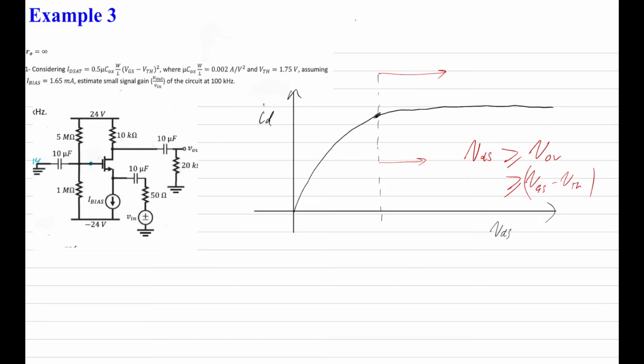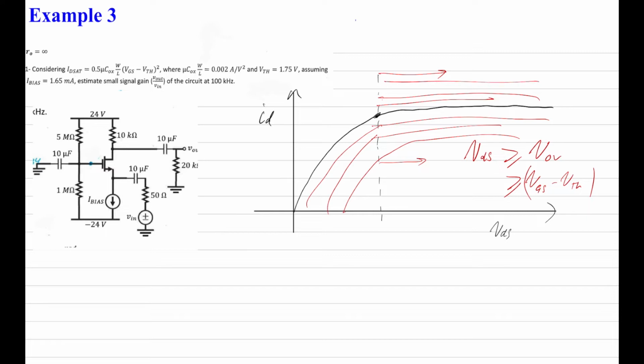So the only thing that really determines where this level is, if it's over here, or like that, or like that, is actually determined by one parameter, and that's the gate source voltage. So once we are in this region over here, we can adjust the current flowing through simply by adjusting the gate source voltage between here and here, okay?